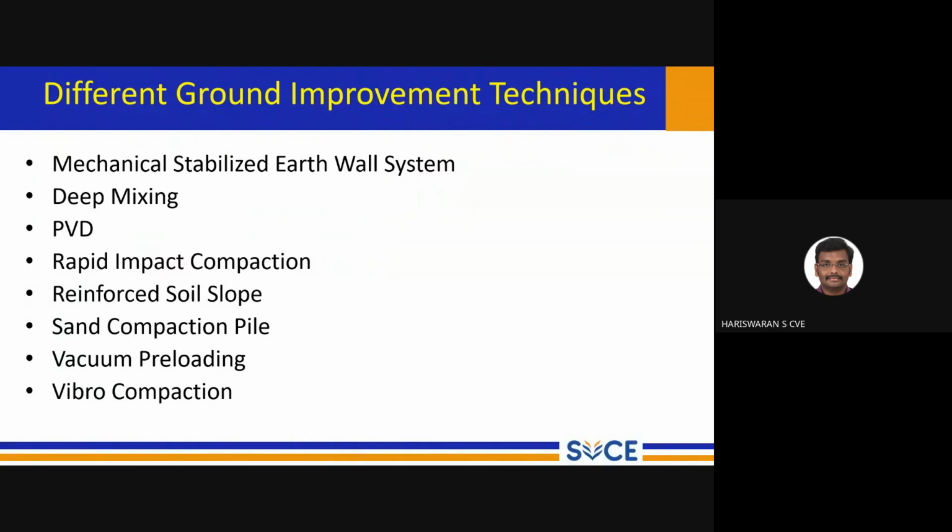If you are going to plan the construction of a high rise building or industrial building, we are supposed to apply very large loading, but the soil is not capable of taking the load. Maybe that can be stabilized by incorporating sand piles or stone piles or any other pile foundation. But the problem is saturated clay: when we apply the load, it slowly undergoes consolidation. The removal of water from the voids is going to happen. So the preloading technique nullifies this problem.